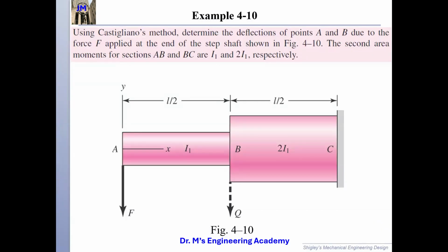So for any point, let's see for the free-body diagram here. So this is O, and this is X. Here is half L, another half L. Now, for any point X here, I know the sum of moments equals 0. You agree? Because I know this beam is in a state of equilibrium, right?